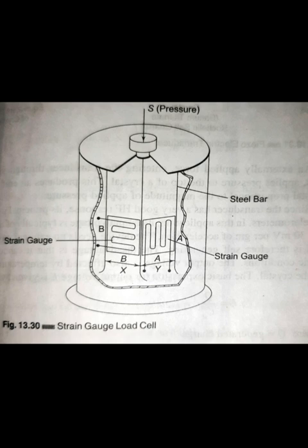That means increasing the number of strain gauges applied magnifies the small changes into more measurable ones. A set of 4 strain gauges in a specific circuit is the application of the Wheatstone bridge. The Wheatstone bridge used for load cells is a configuration of 4 balanced resistors with a known excitation voltage applied.